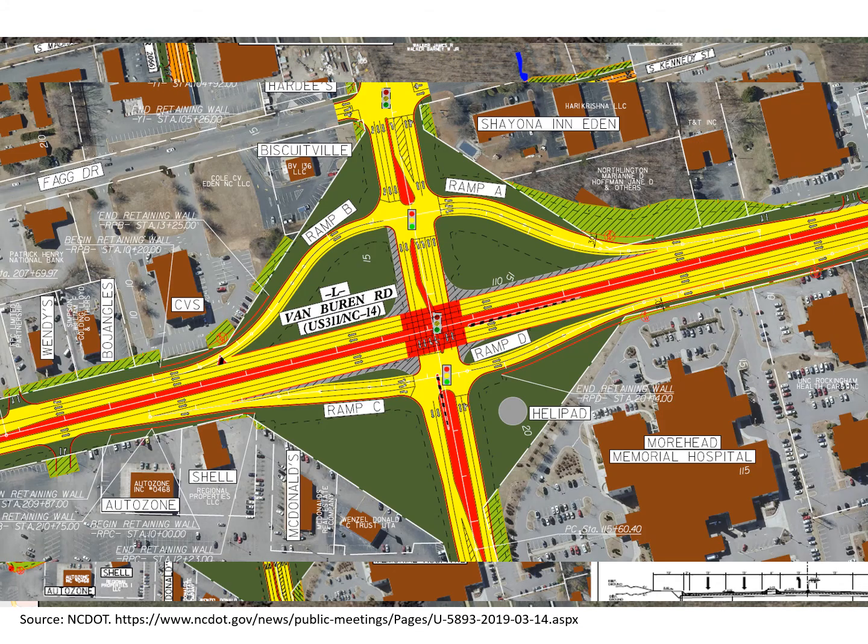And finally, one of the other alternatives considered was a modified compressed diamond. So this is using those ramps, so exits and entrances, to remove those left turns from that main line and grade separate this intersection. So these are some of the options that can be used to reduce or eliminate the left turns, and ultimately it's part of those solutions when you've reached the end of capacity from a traditional signalized or even unsignalized intersection, and you need some other alternatives to either operate traffic safely or efficiently. Hopefully both of those improve their safety and operational performance.